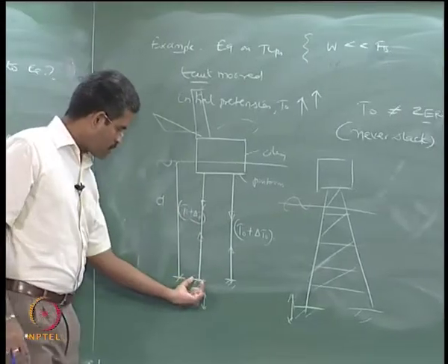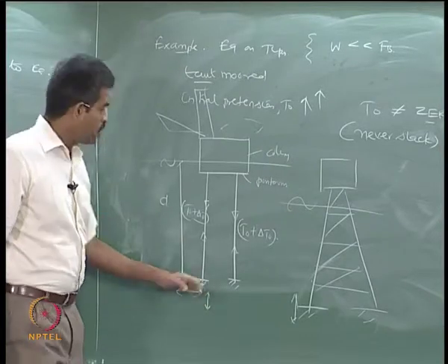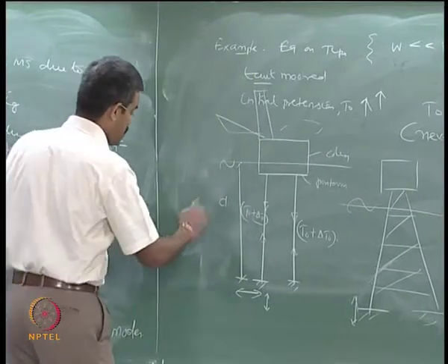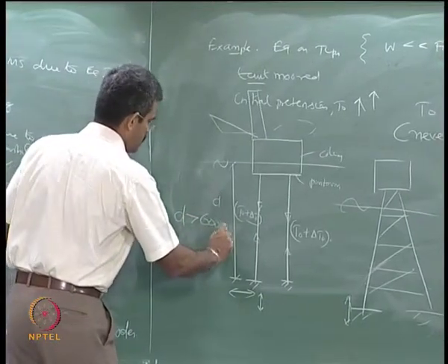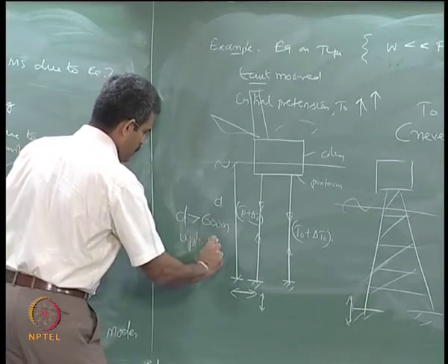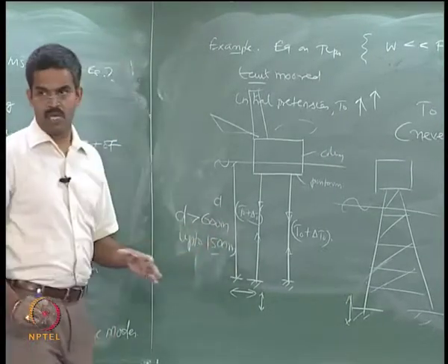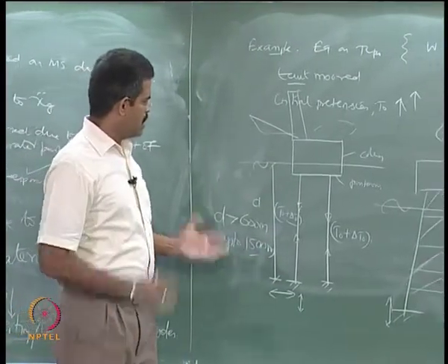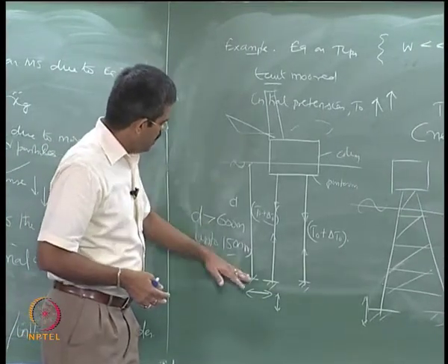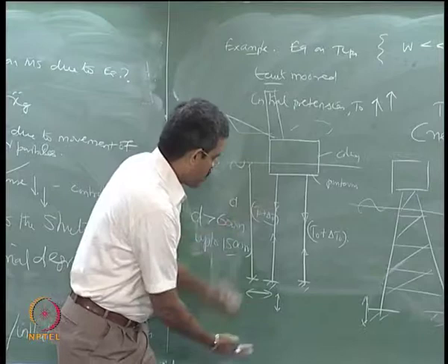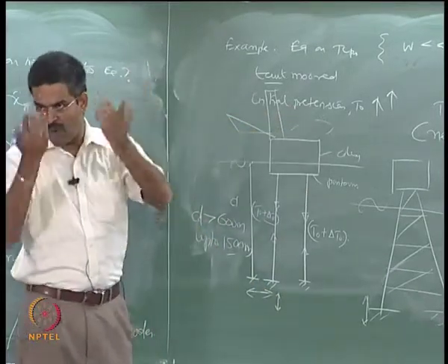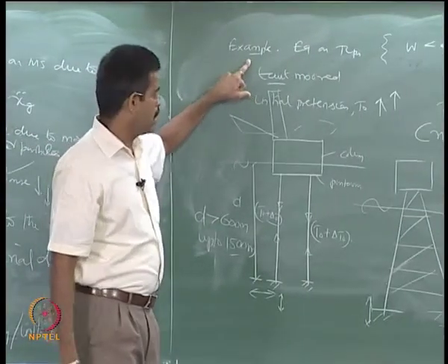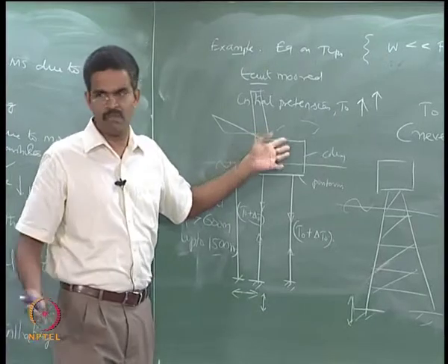Whereas in this system, I have earthquake loads here and a huge water body, because compliant structures are generally designed for depths exceeding 600 meters, up to presently 1500 meters, a very large and very deep water body. Therefore it is seen physically that the water depth will try to dampen the effect of the earthquake on the superstructure; that is the general belief. So we will take an example very quickly in a few minutes to explain how the forces are transferred to the superstructure and what spectrum is being used.